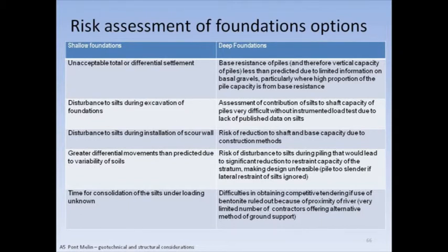The shallow foundation issues, the issues we've highlighted about differential movements, disturbance, and the possibility of differential movements for whatever reason, for example, the variability of ground conditions between the different abutments, and this issue of the possibility that settlements may occur over a long period of time outside of the construction period and therefore be difficult to accommodate. Those are things which, whilst they presented significant risks, we felt that we could address by a proper strategy of investigation and by ultimately considering the construction sequence.